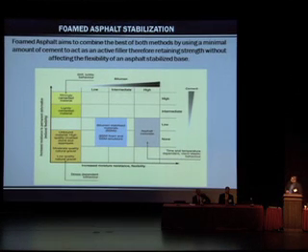Okay, so foamed asphalt aims to combine the best of both methods by using a minimal amount of cement to act as an active filler, therefore retaining strength without affecting the flexibility of an asphalt stabilized base. As you can see here, what you want to do is land in between, just slightly lower than your cement treated base and slightly less than your asphalt concrete.